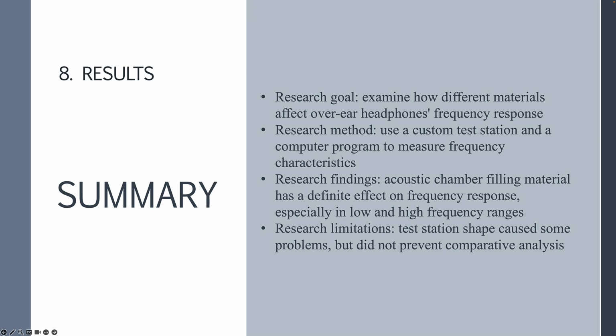Due to the growing interest in high-end audio products among users and the emergence of numerous companies manufacturing or modifying headphones, investigating the acoustic properties of the materials used in production appears to be crucial to designing commercially successful models. The primary aim of the research was to determine the effect of different materials filling the acoustic chamber of over-ear headphones using a custom-built and printed test station and, using a computer program, to make measurements of the frequency characteristics. The research has shown how much influence just one of the many elements of headphones can have on their final characteristics. The measured characteristics made it possible to draw conclusions and revealed certain trends.